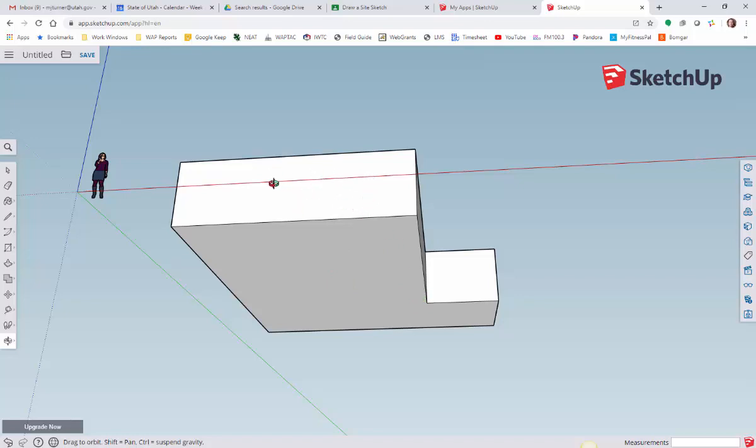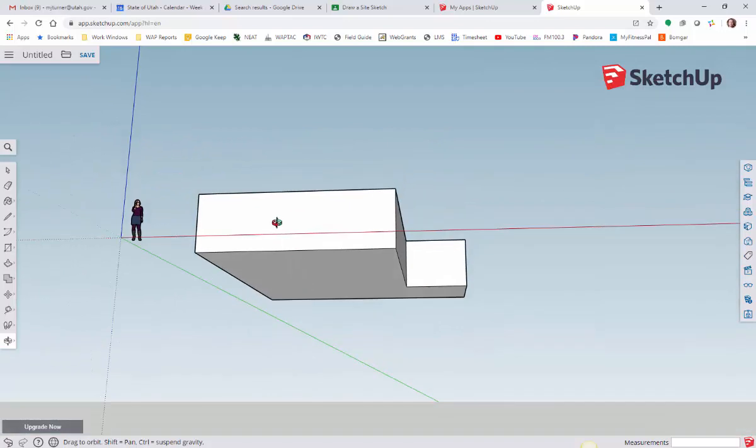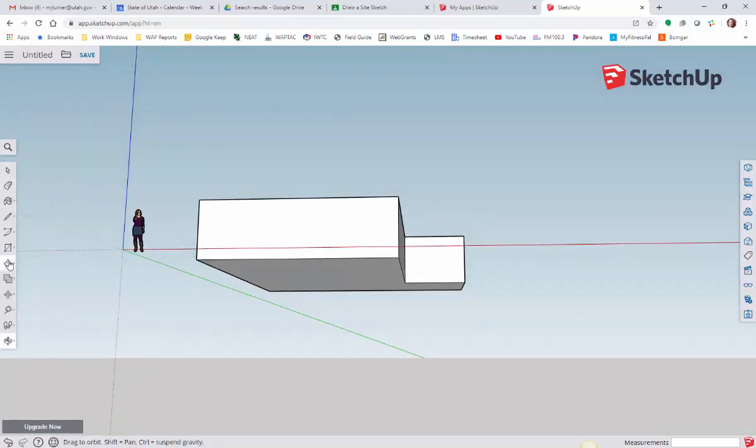And when I'm done, I'm going to want to be able to separate the area of the main floor from the basement. In order to do that, you need to actually group this main floor into a group so that when you start drawing other components, it doesn't attach those components to this component. You can draw them right next to it, but it won't attach them.